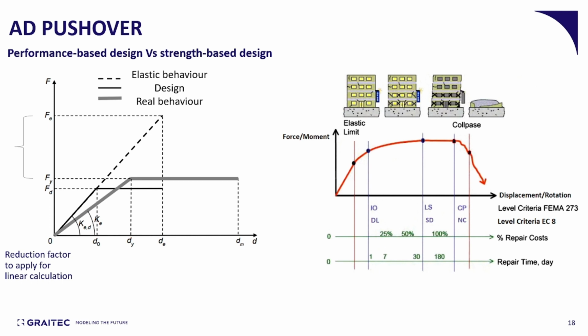For example, a very old structure. We don't mind after the earthquake to have extensive deformations, extensive damages. We are not planning to repair this structure. We are happy to demolish it after the earthquake if it is damaged extensively. However, we would like the structure to be able to develop its internal forces and resist the earthquake.